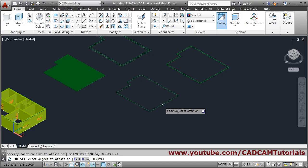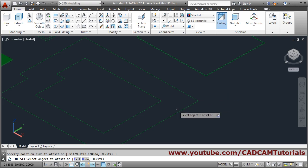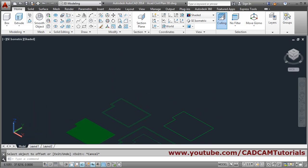And then for the compound wall, we will offset by 3 meters outside. So select the object, give 3 meters, 3, enter. Then we will offset it inside by 0.3. So again select this line, go inside, 0.3 is already there, just click, then escape to come out.